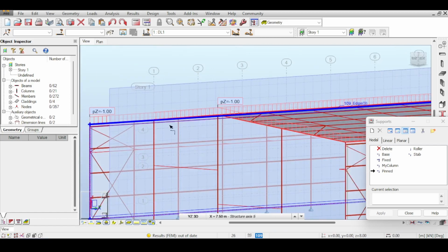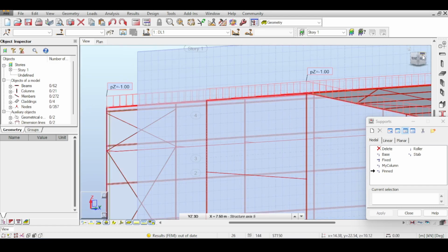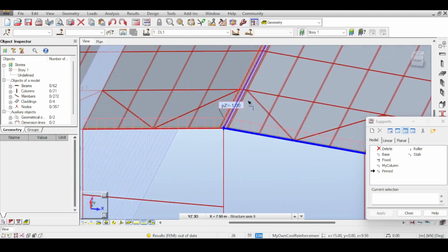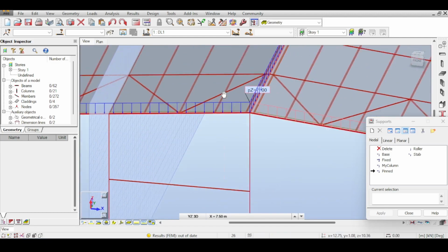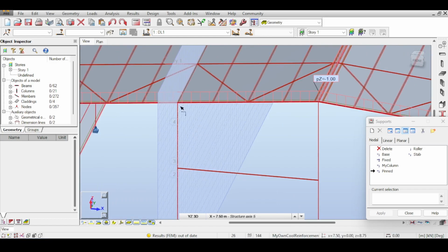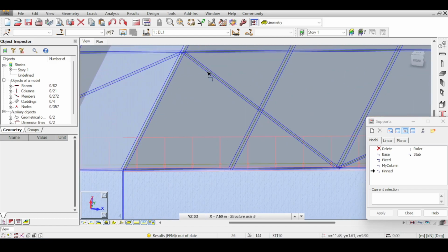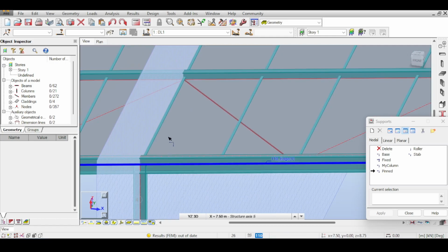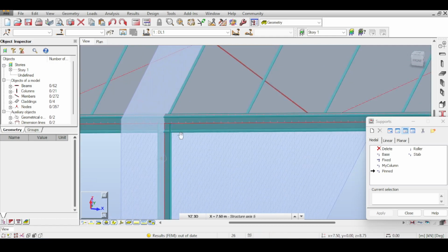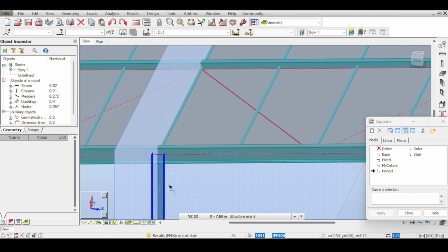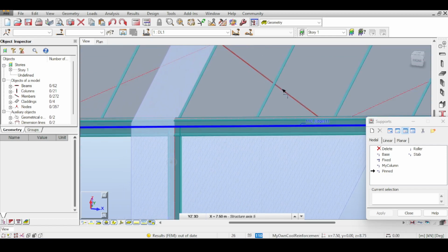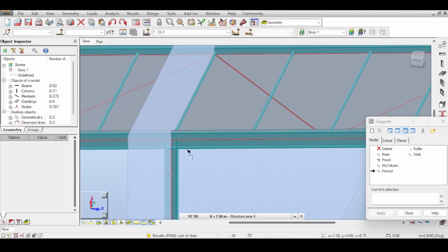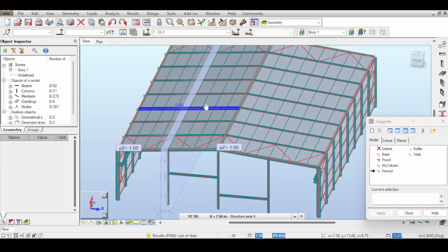You have two options. You either make a frame action between the column and something here, the purlin. No, that's impossible. So some of you told me that, well, actually, those bracings should be touching the column. That's fine, but I'm still unhappy because those bracings are connected to the portal frame section. So even if in the model they touch the gable frame column, and even if touching the gable frame column stabilizes it, in reality, those bracings do not touch the gable frame column, and they should not contribute to the stability of the gable frame column. So I'm kind of like stumped, to be honest.